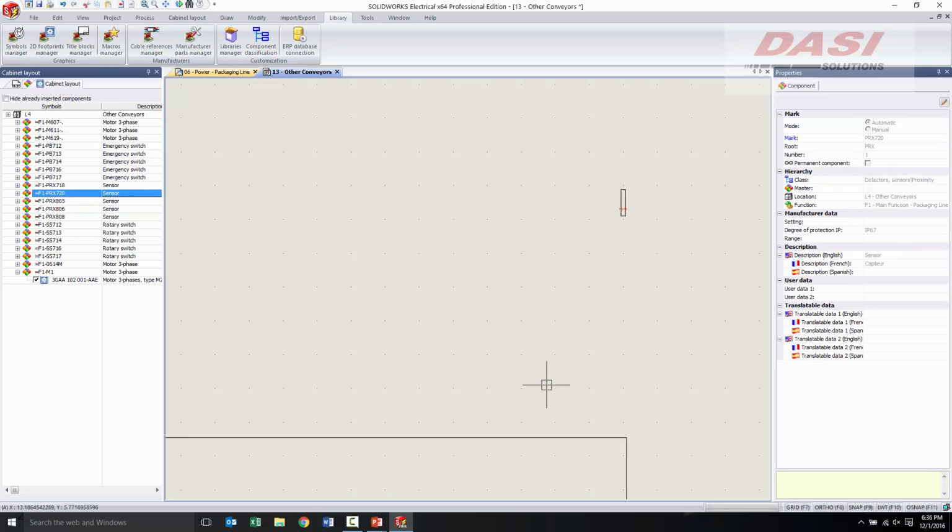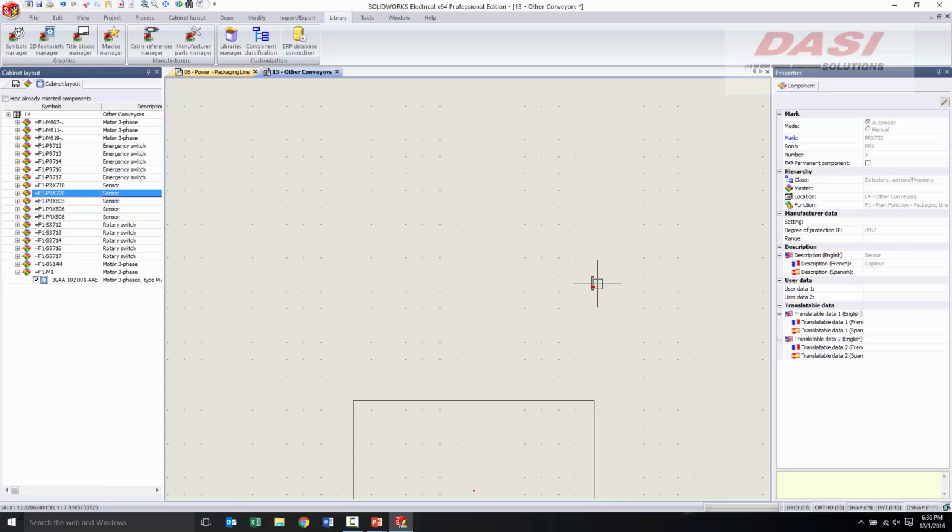Yeah. So if you're now trying to look at where do I run cables, I need to run a cable from here back to the control panel, and then from the control panel, I need to take it back to the motor. And I have to make sure that if it's a collapsing or telescoping conveyor, it stays out of the way of the wheels and all that type of stuff.